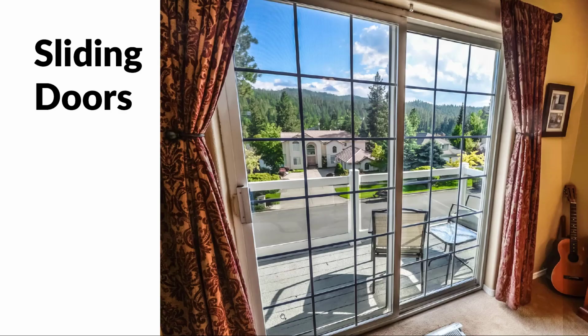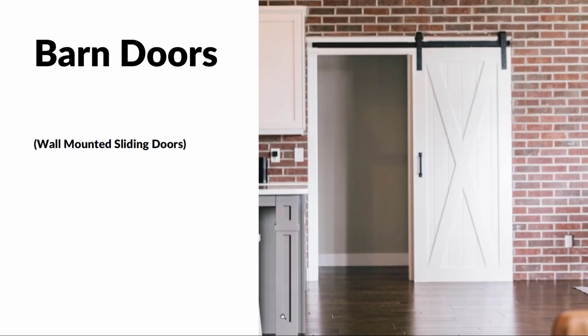We can also have sliding doors. Sliding doors are very much like sliding windows, so they slide horizontally back and forth. They're really space saving both on the interior and exterior because you don't have to have space where they swing in or out of the room, but they run parallel to each other in a track. They're very common on patios, decks, balconies, areas like that, and they're very commonly all glass or mostly glass, especially in that application. Sometimes we have sliding doors on closets and things like that, and then those are usually solid.